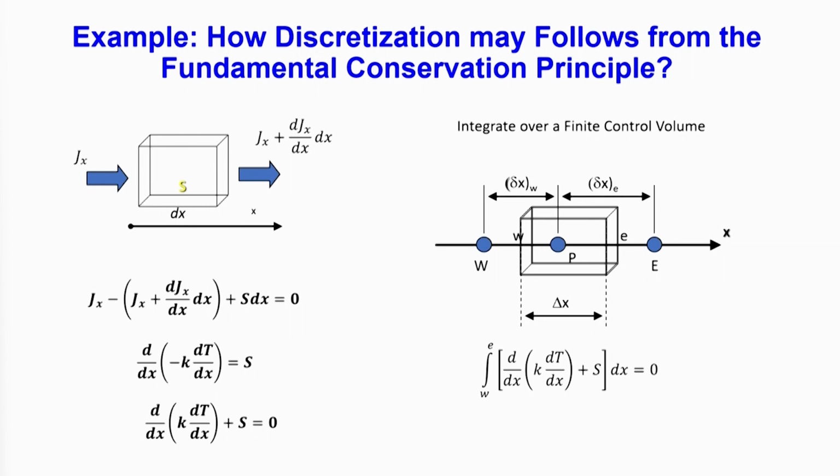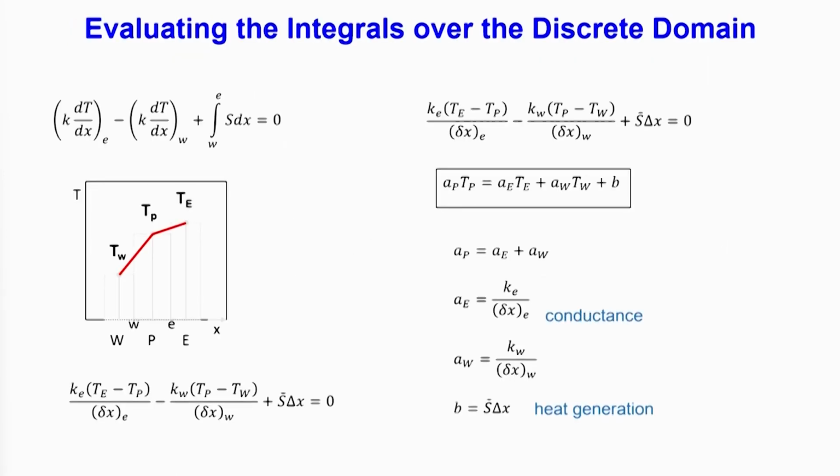Piecewise constant temperature is even a further simplification of a general linear variation. So, we will see whether that creates any problem or not, because otherwise it is quite simple to do in terms of the analysis. So, if your source term is a function of temperature and temperature is constant, you can take it out of the integration and integrate the dx. If you do that, we will get back to that slide.